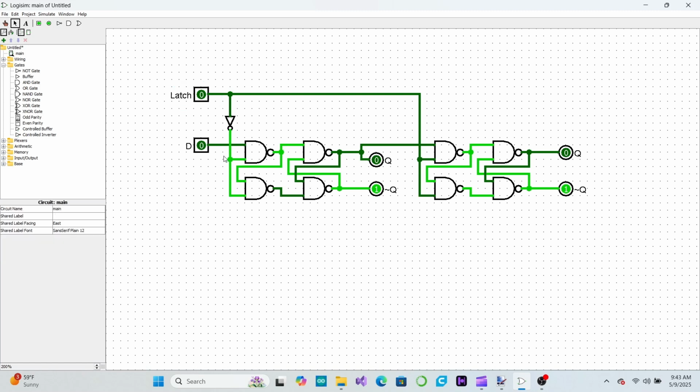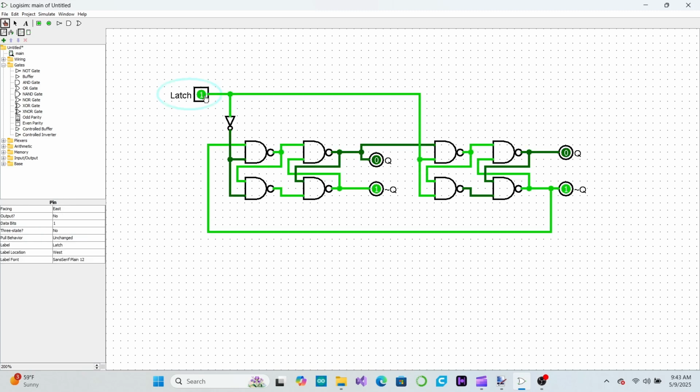If we now try what we did before by connecting the inverted output of the latch to the input, we see that it works perfectly, causing the latch to only change state at the instant the latch input goes from 0 to 1. This behavior will be extremely important when we add memory circuits to our CPU in a moment, because it allows us to precisely control the exact instant when data will get moved around the machine.